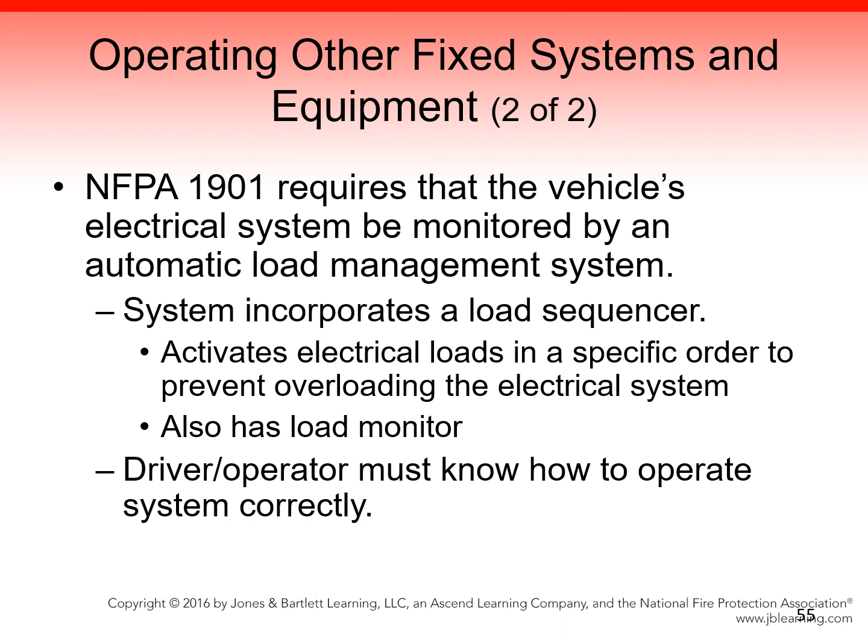Many new fire apparatus have complex electrical systems whose outputs will exceed the alternator capacity and can be supplied only by the deep discharge of the apparatus batteries. These high-powered batteries experience serious damage when they are deeply discharged. The automatic load management system, therefore, is designed to protect the electrical system from needless damage while maintaining the operation of essential devices.